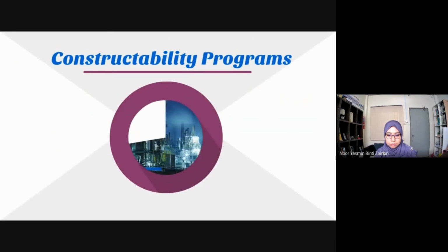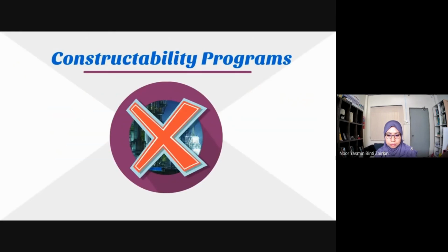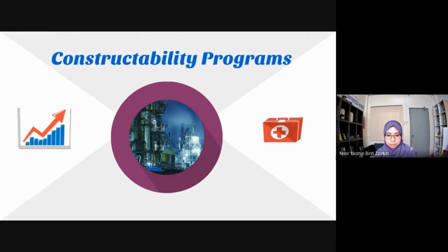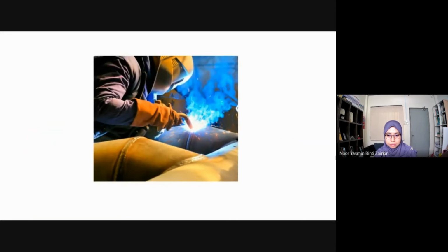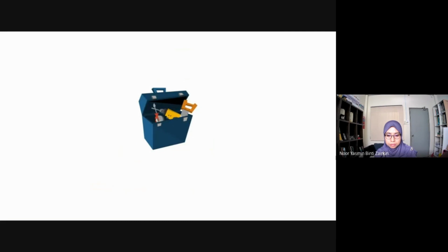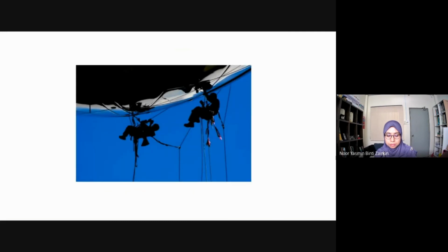Constructability efforts allow you to optimize engineering design to minimize construction work done on site and allow you to ensure that work done on site is safe and efficient. This includes improving field build locations, kitting studs, nuts, gaskets, and insulation of module interconnect locations, and leveraging rope access personnel to minimize scaffold costs.